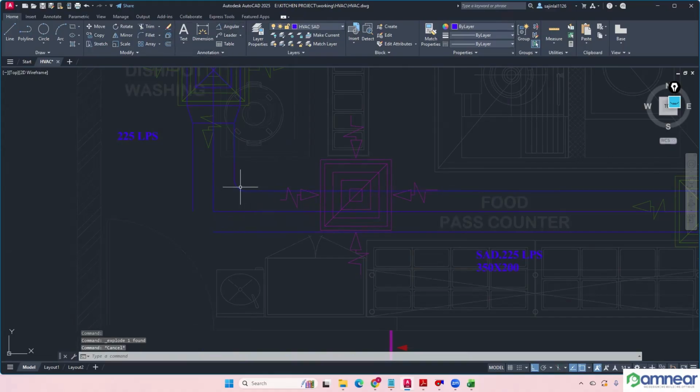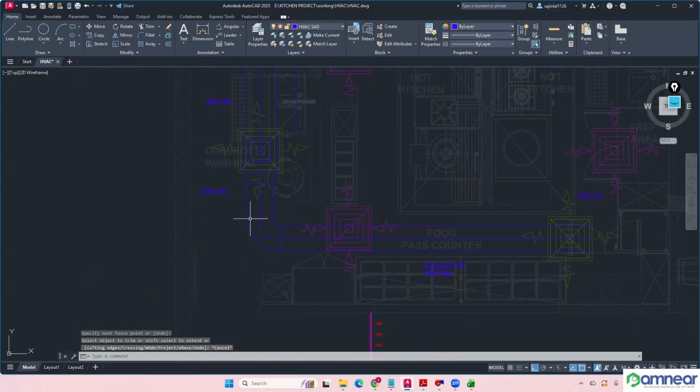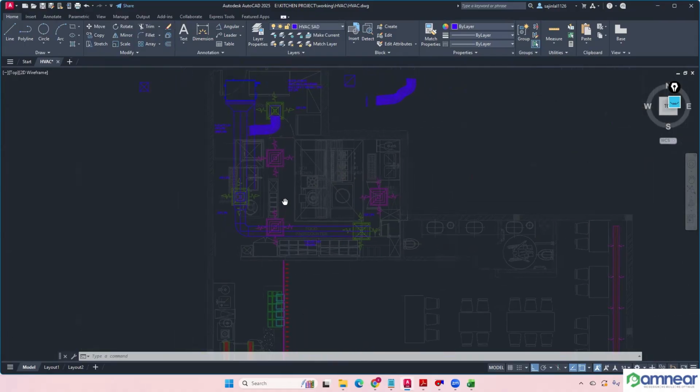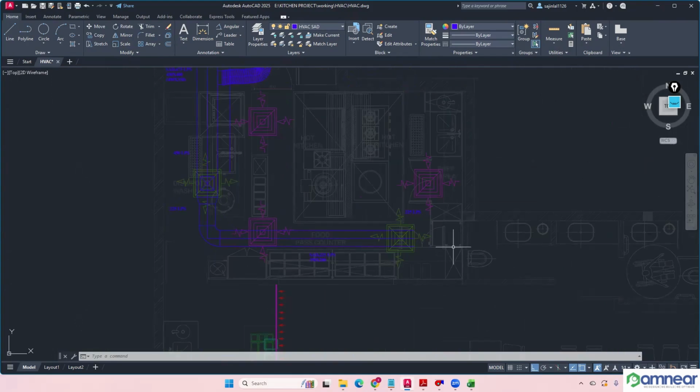Slightly explode it for the time being. Later we can join. And the width of duct is like how much? 350. So offset, width is 350 enter. So we can offset this side. So trim this one and trim this one. Take a polyline and close this. Okay, fine. Instead of this elbow, we can do one thing. We can extend this duct up to here. From the duct side, we can propose a shoe collar. Through the collar also we can connect, but the pressure drop through the shoe collar will be slightly high. So that's why I'm not proposing it.